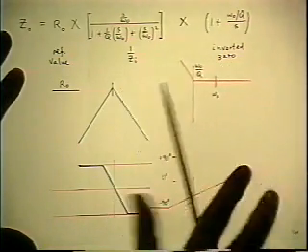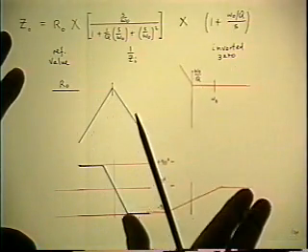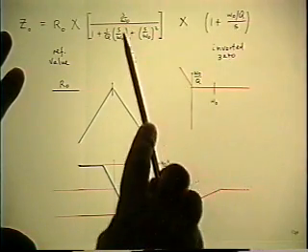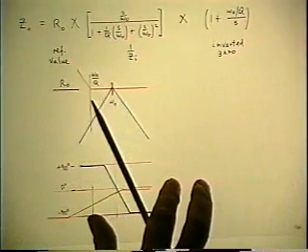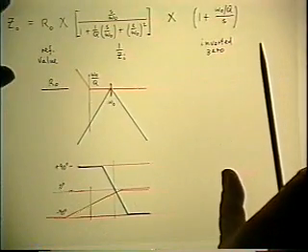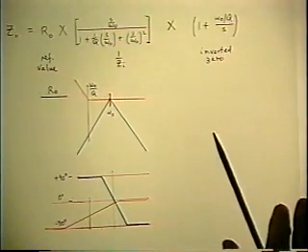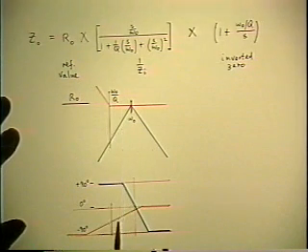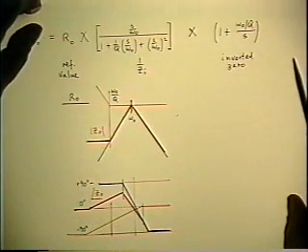So vertically, the flat part of this is 0 dB for its own function, so that has to line up with the R0. And again, the omega 0 of this function is the same omega 0 as is in the quadratic, so I have to line it up horizontally like that. So once again, all I have to do is add the orange and the blue lines, both magnitude and phase. And so now the result looks like this.